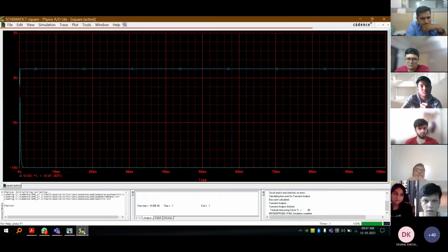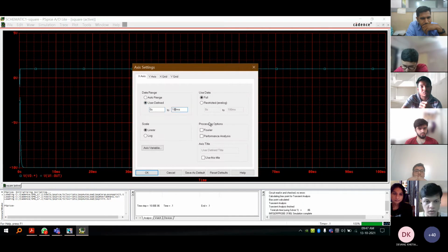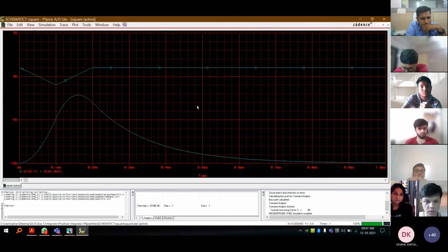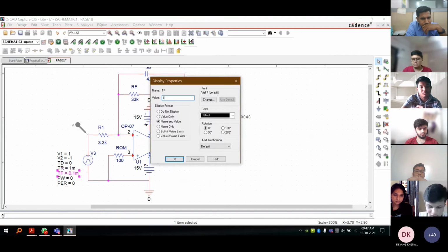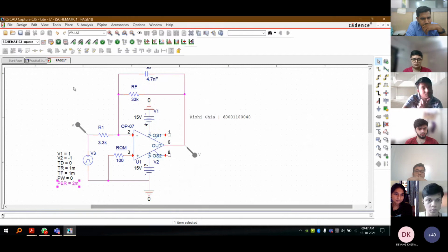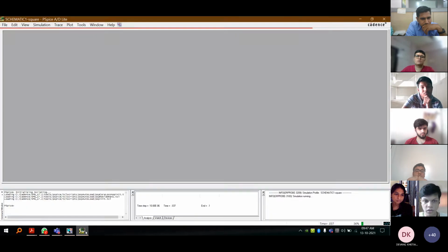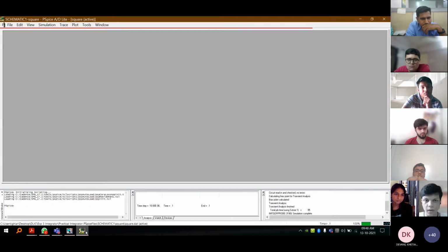Give it a moment. Okay, so this is too much, I'm just going to reduce this to, let's say, 1 ms. Sorry, I'm facing the same issue we faced earlier. Just give me a second. My rise and fall time, and oh yeah, the period has to be twice of your rise or your fall time. I think we should have it now. There we go, we do have it.